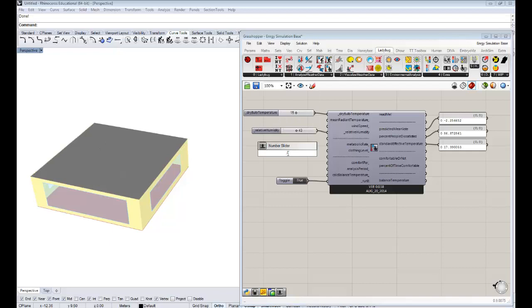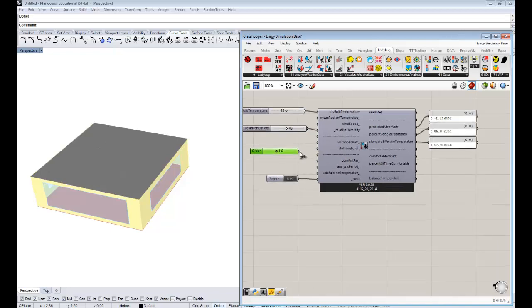That's about shorts and a t-shirt, and the maximum that you might wear, one clo, which is what you input here, is a 3-piece suit. But maybe we can go up to 2, which would be like 3 layers of clothing, something pretty thick. We're saying that we're in a climate where people actually are okay with this. So we can first start off with 1 clo, and it doesn't change too much.